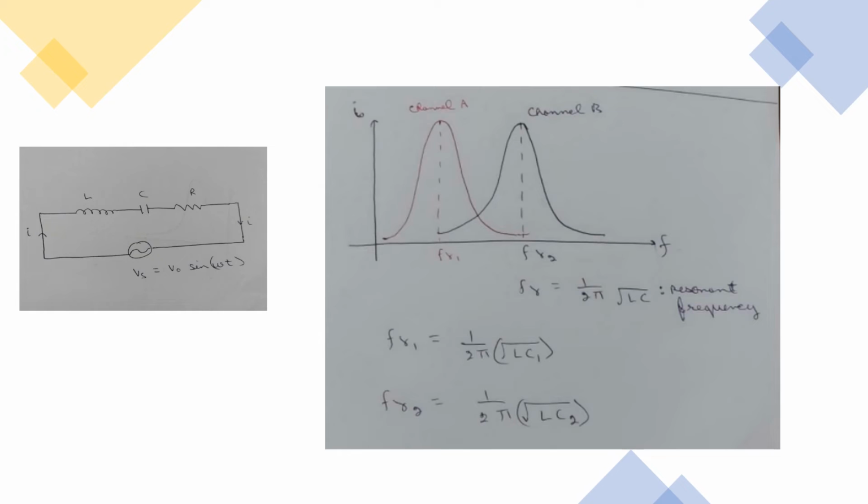As a result, the antenna vibrates with both the frequencies, and what an antenna does is basically convert radio signals into electrical signals. So, because of these two, the antenna is trying to drive our LCR circuit at both these frequencies. But look from the graph, we can see that the message coming from R2 is able to generate much larger current from channel B as compared to channel A. And as a result, very high current of channel B flows through the speaker, whereas low current from channel A will hardly drive the speaker.